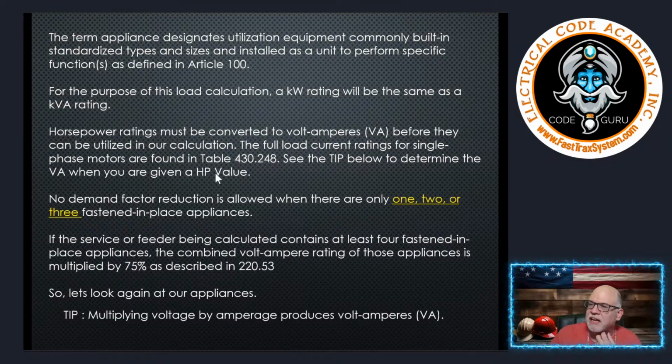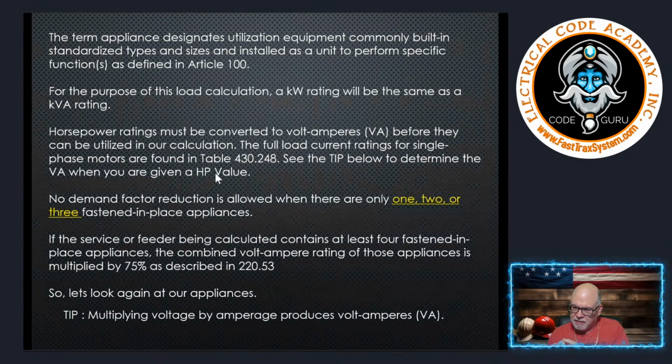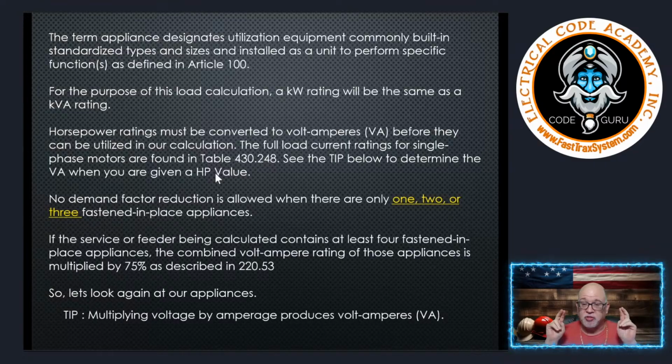So let's go look and see what we got. Okay, now the first thing that we also want to remember is that typically in residential calculations like this, anything with a HP or horsepower rating is a motor. But a trash compactor, dishwasher, things like that, we don't consider as motors. And that's important later when we're looking for the largest motor in the dwelling. So make sure you understand that when you go looking for the largest motor later, you definitely want to make sure that you're looking for a true motor.